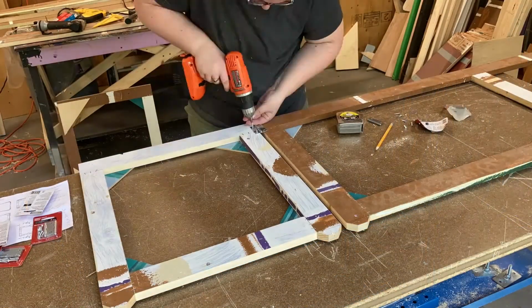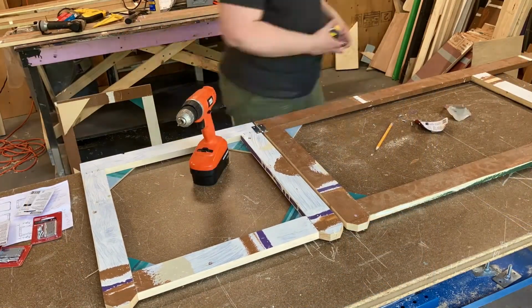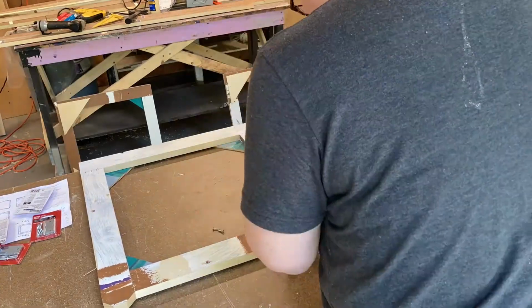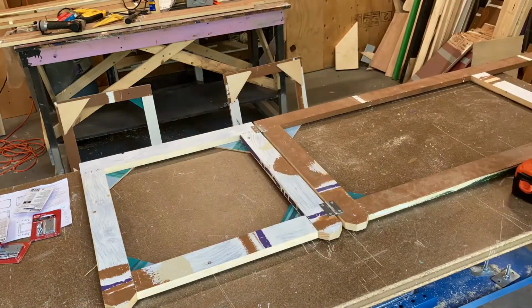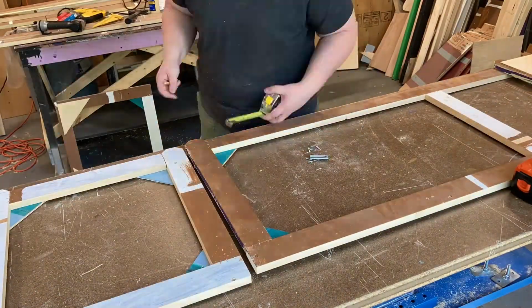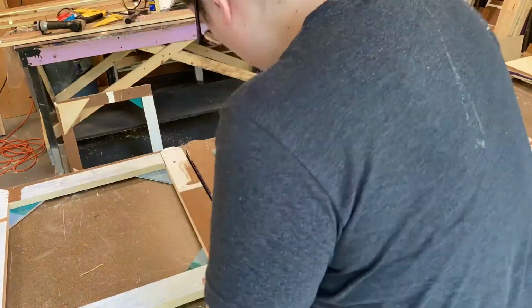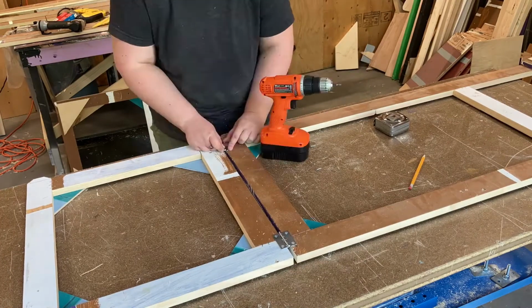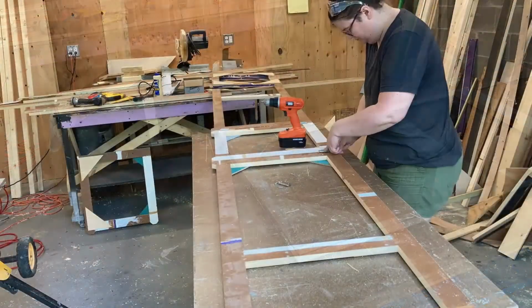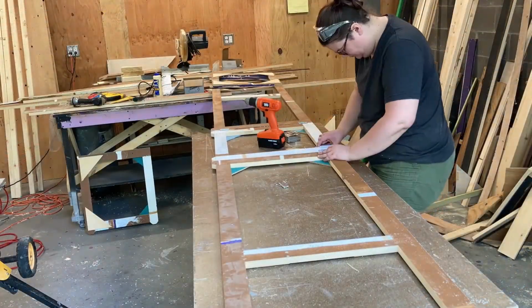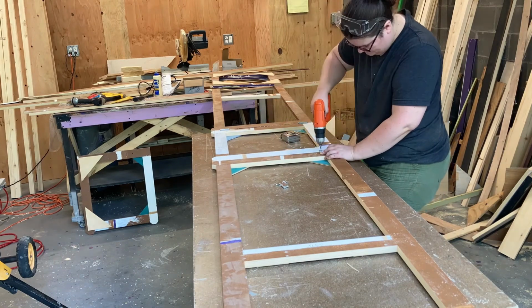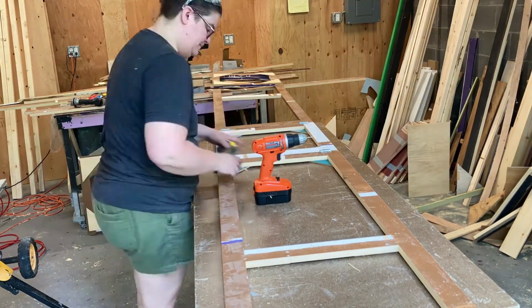With all frames built and braced, it's time to assemble them into a 3-dimensional object using hinges. For this project, I'm using some small utility hinges, a little smaller than I originally planned for. Any back flap hinge will work as long as all hinges used in the project are the same. If you mix and match different pin sizes, your pivot points will be ever so slightly askew, and the action of the parallel won't be as smooth.